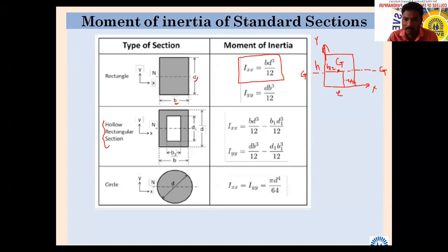So once we pass Ix, meaning a horizontal axis parallel to the x-axis and passing through the centroid, that is Ix we will say. Once we want to find the moment of inertia about that centroidal horizontal axis, the dimension which is going to be cut, we have to make the cube of that, you should remember. For this Ixx, which dimension is cutting, whether the vertical dimension or the horizontal dimension is cut by that axis.